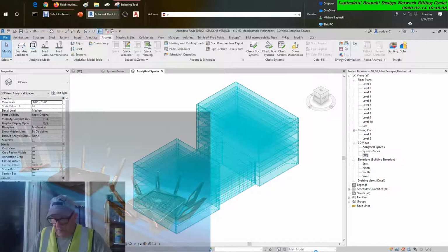Using either option will open the Insight 360 tool showing your energy model results. The energy simulation run will be stored in the All Uncategorized folder. At this stage, the run has not been associated with a project. Before you review the analysis, let's first create a project.